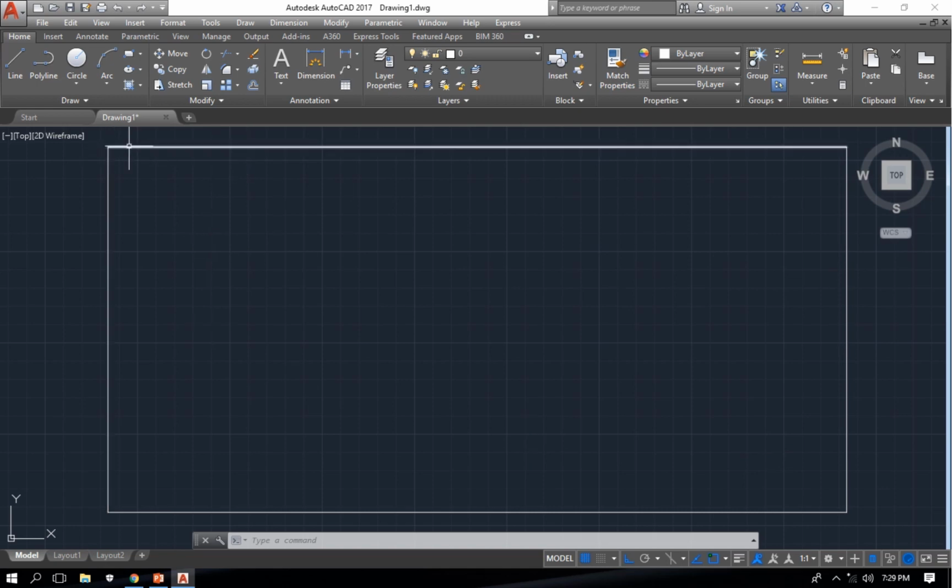And first thing we're going to do is to create layers. I'm going to create layers for every property we want to have in our layout. So these lines for the rectangle will serve as the boundary, while we're going to have a layer for our plots and roads, because basically in every layout you have plots, you have roads, you have facilities, you have services, and you have the boundary. So these things are all going to have a separate layer in order to make your work easier.